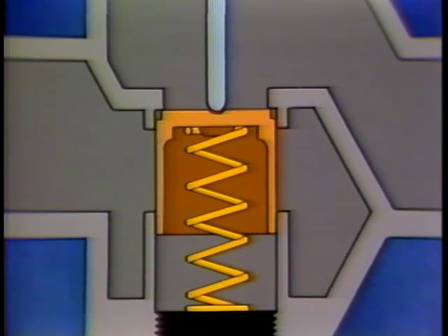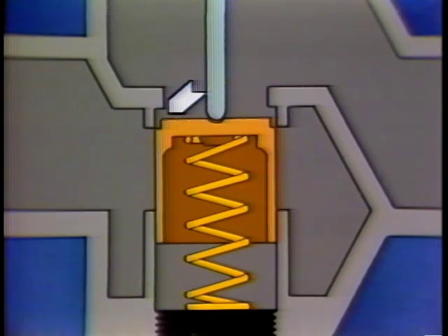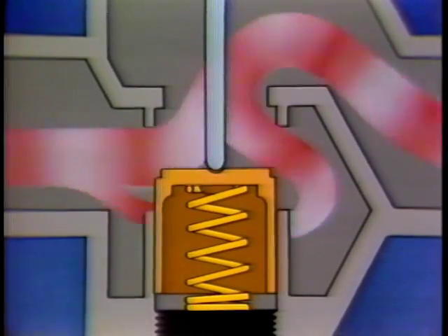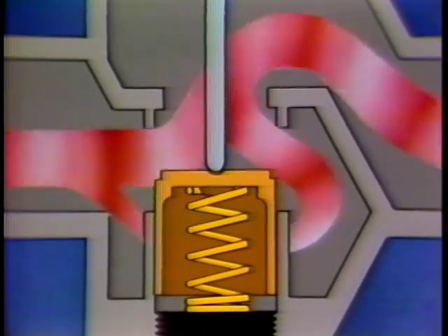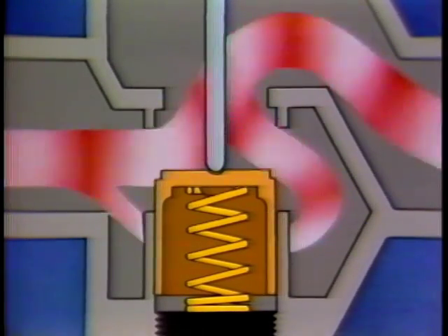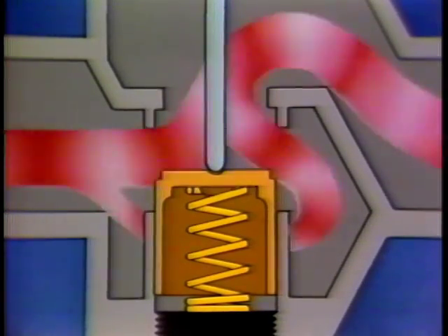a cage valve in which the shutoff surface is independent of the fluid control surface, which is 4 circular ports in the side of the cage. The valve must move off the seat or sealing surface before the flow controlling port is opened. The sealing plug is off the seat before flow begins. Therefore, the wear caused by high velocity flow through a partially opened valve at startup or at low flow operation occurs only at the flow control port and not at the shutoff sealing surfaces.